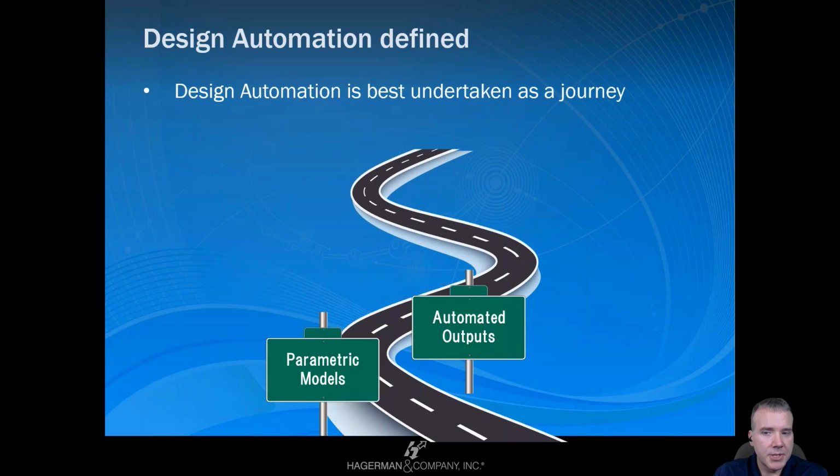So a sort of side path on the automation journey, in my mind, is automating what I call outputs, meaning say a PDF of a drawing or a step file of a model, a bill of materials from a parametric CAD modeler. Automating outputs. So you generate your models, you generate your drawings, and now you need to share a PDF, a step file, a flat pattern DXF.